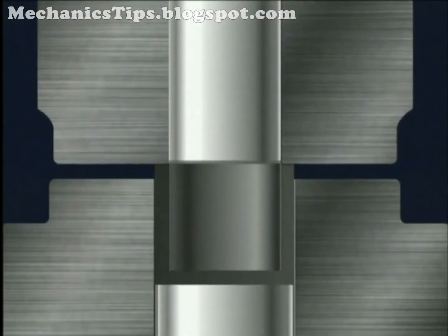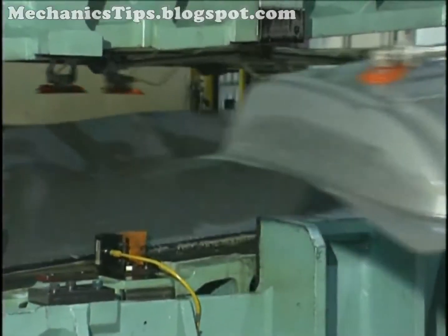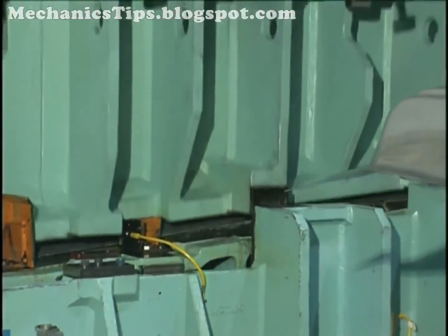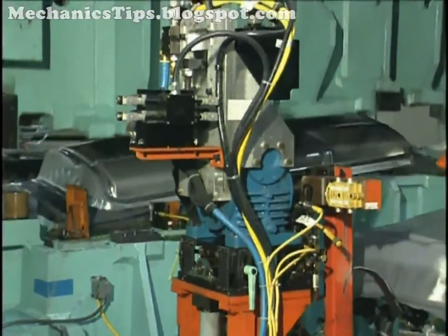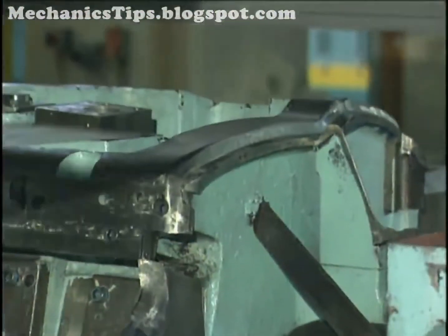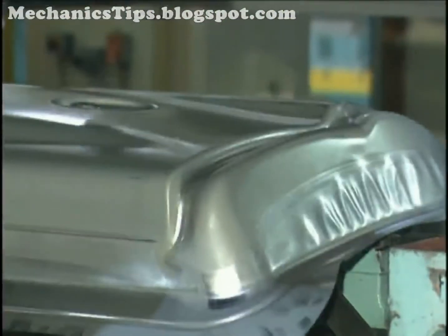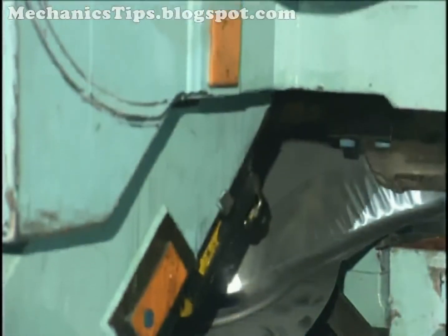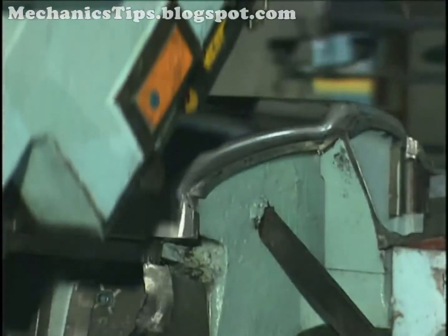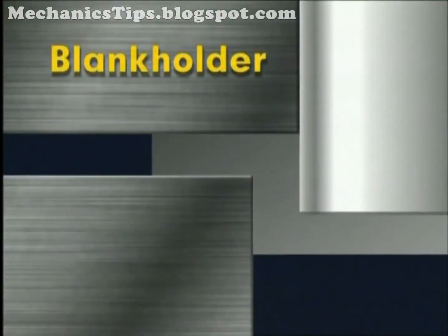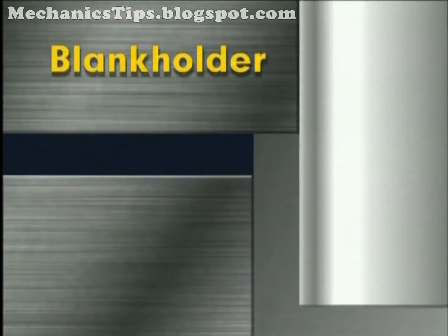Additionally, the drawn metal must have a combination of strength and ductility to avoid rupture in the critical area where the metal conforms from the punch face to the punch sides. Compressive forces on the metal in the area beyond the die's edge will cause the metal to buckle. If this metal were pulled into the die, buckling would increase until the metal ruptured. To prevent buckling, the blank must be held tightly by a blank holder.